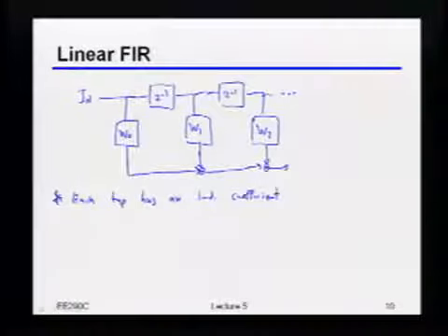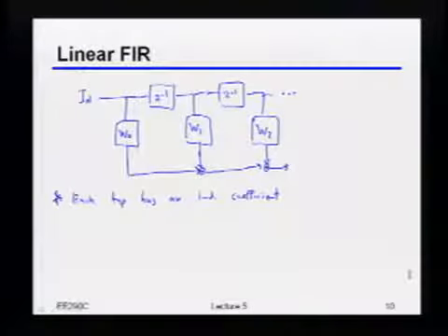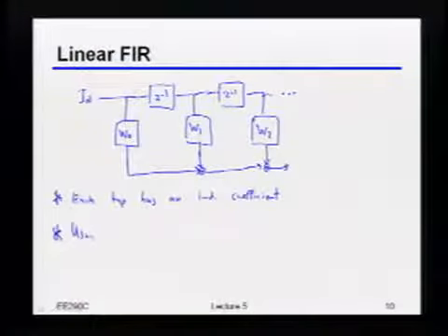So that just means that it's slightly more flexible, or perhaps even a lot more flexible depending upon how many taps you have, of course, in terms of trying to create these weird-looking shapes. Because basically by futzing with a combination of these 3 taps, you can create some shape that looks very strange versus what you could do with a straightforward continuous time filter like we had in the previous example. That's really the biggest differentiation there. The other thing to point out is that this is usually done at the transmitter.